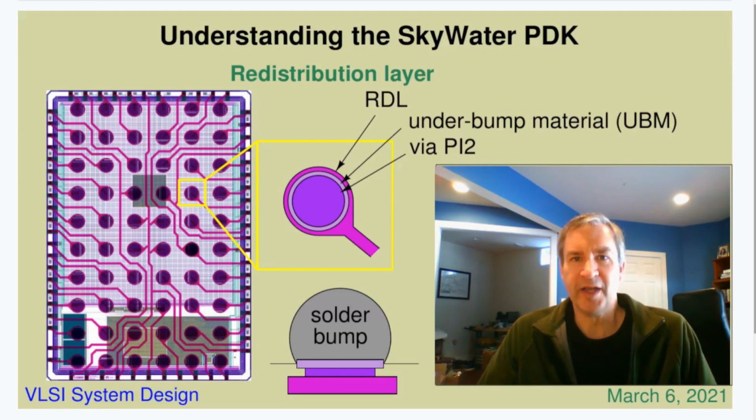The redistribution layer is usually not a design layer and is considered more as part of the chip packaging. However, the copper layers are thick compared to the underlying process back end, more than 4 microns thick, and can be useful for forming inductors on the top of a chip. In any case, analog designers have to be aware of any redistribution layers on top of a design, and in addition that the chip is flipped with circuit board, power, and ground planes directly underneath.